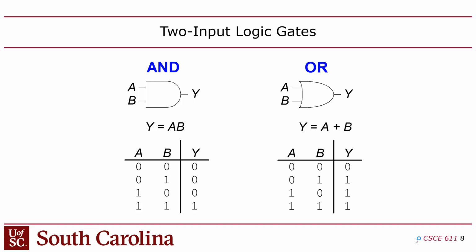So if you had these 2 gates in a design, you can't connect that to that. That's really bad. That's a short circuit. You don't want to do that. It's also called contention, right? Because every module that you have in there will have outputs, and when you connect a module's output to a net or to a wire, that module becomes the driver of that net.